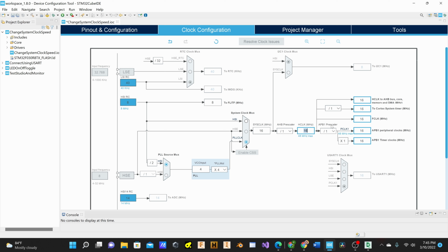You can change prescalers, dividing the clock further if you want to. You can divide the clock over here, which goes back down to 8. You can divide it over here. You can change some of these features or peripherals to different speeds. We're going to maintain a non-division.